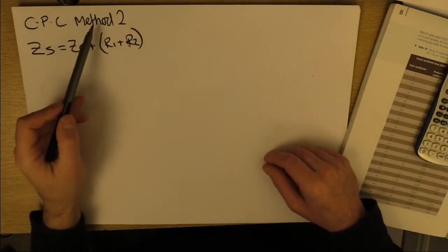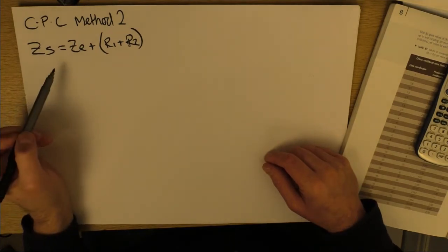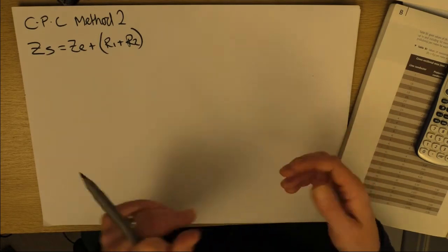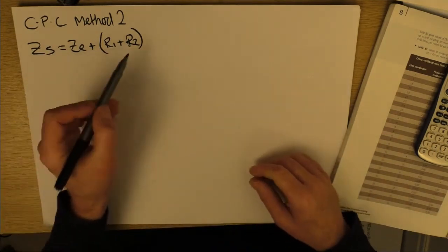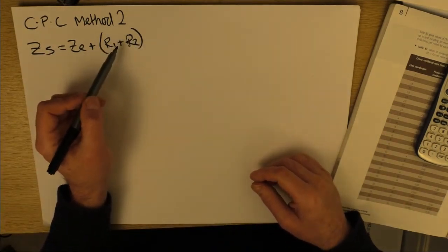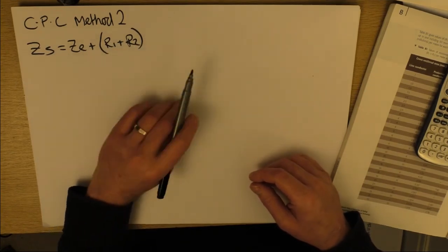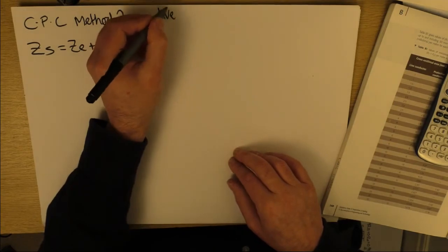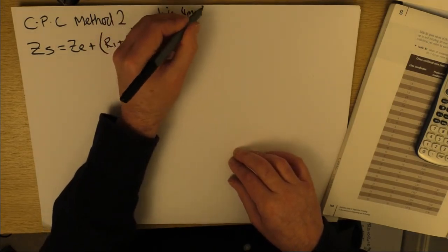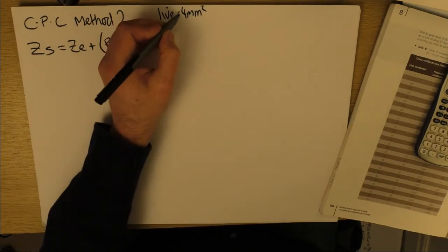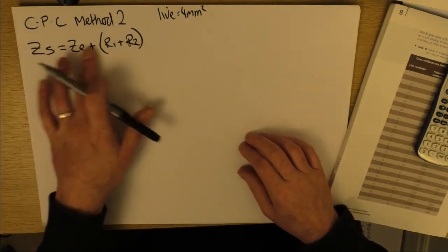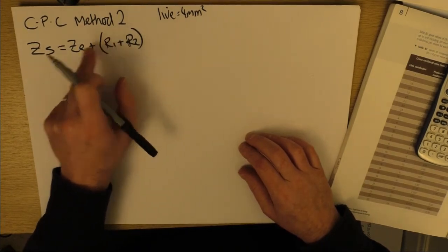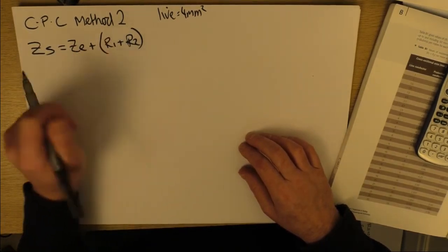Okay, so CPC Method Two, very similar to Method Two using the volt drop. We're going to rearrange this R1, R2 equation for maximum milliohm per meter. And we know that our live cables are 4 mil. So this is about choosing the CPC. So we need to play with this and find out how to transpose this really to get maximum